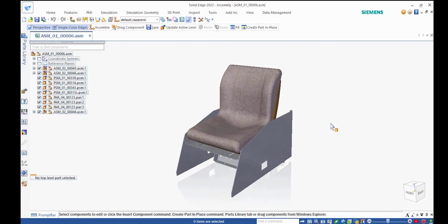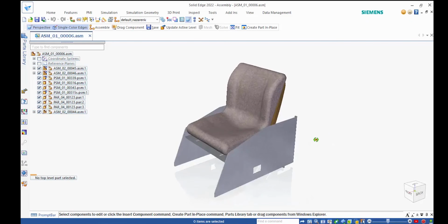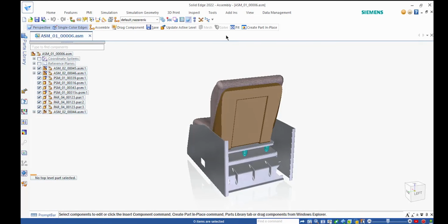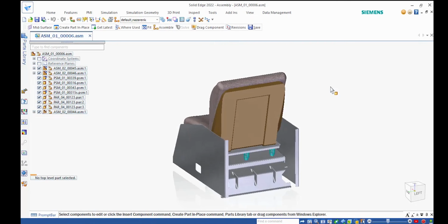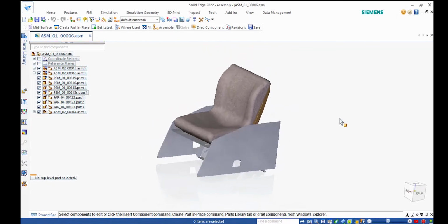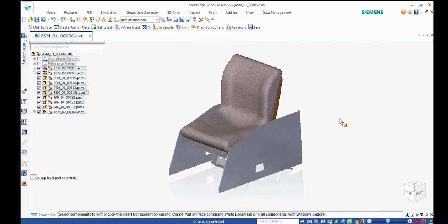As I mentioned, this requires a special type of mesh, shell elements, and we're going to focus in this segment on this particular task at hand. So what we're looking at is a supporting structure for a lawnmower. As you can see, the seat transfers load through this plate and via the springs onto the lower structure, and we need to evaluate whether this supporting structure is capable of supporting the specific weight.